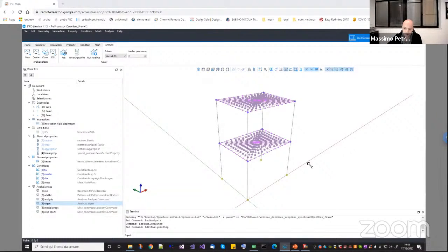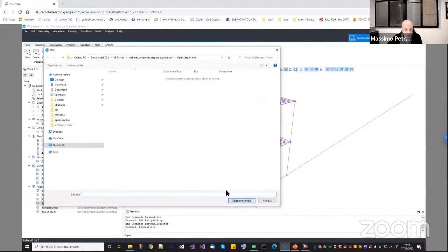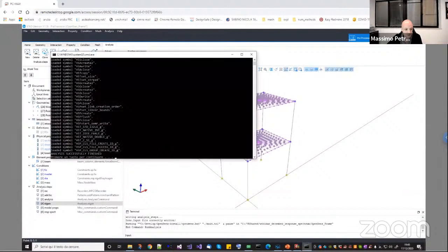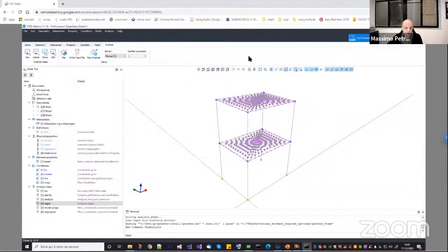So at the moment, if you want to make sure that everything is correct, assume that your model is elastic. So in your case, when you have 2 trusses, just model one of them. If I run the eigenvalue analysis here, it should be fine with 7 eigenvalues. This is the output that you have now with OpenSees. At most, you have the number of eigenvalues that you want, but you don't have anything for the modal properties.